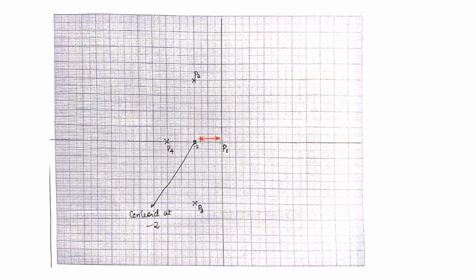Now what about the next region, from here to here? Is this a region of root locus? No, this is not a region of root locus, because suppose we consider a test point here. To the right side of this, what is the total number of poles and zeros? I have 1, 2, 3, 4. Isn't it an even number? The total number of poles plus zeros is 4, which is an even number. So it cannot be a root locus region, that is from minus 2 to minus 4.